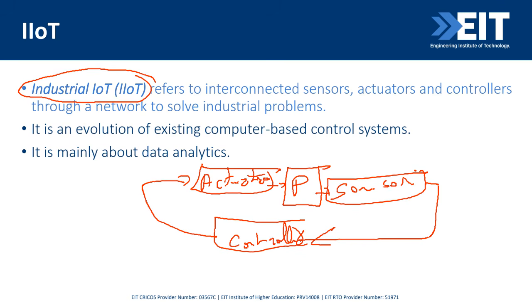Okay, so my sensor might be measuring temperature. My actuator is a heater, so I start or stop the heater, and the process is the room that I am in. Okay, so my controller is always going to compare the current temperature that we have, eventually, to a set point to make a decision and send it to an actuator. This is a very, very typical architecture that you have when you are automating something. Okay, so sensors, actuators, controllers are everywhere in industrial applications.